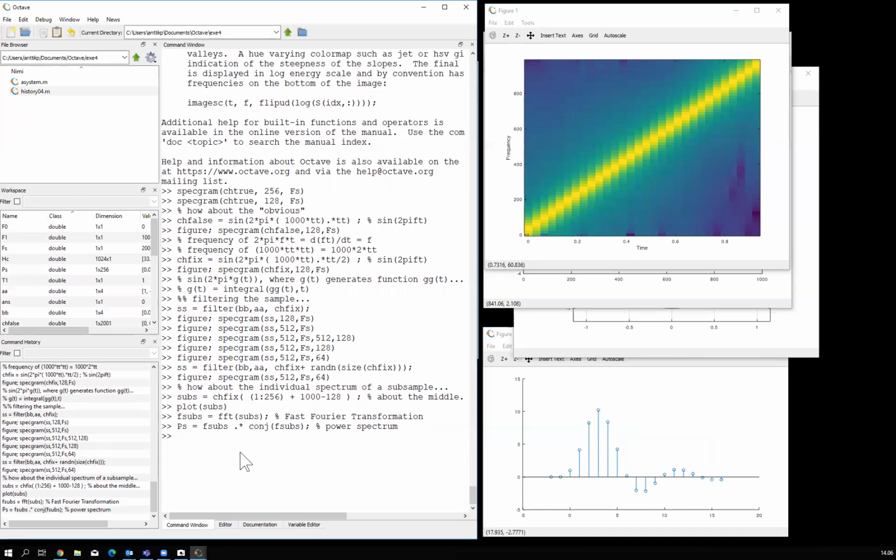The corresponding frequency axis would start from 0 and end at 255 divided by 256 times the sampling rate. So it's a linear transformation. Basically, the sampling rate is the fundamental highest rate on the data. So it has the negative frequencies there too. That's why it is not just up to the Nyquist rate.